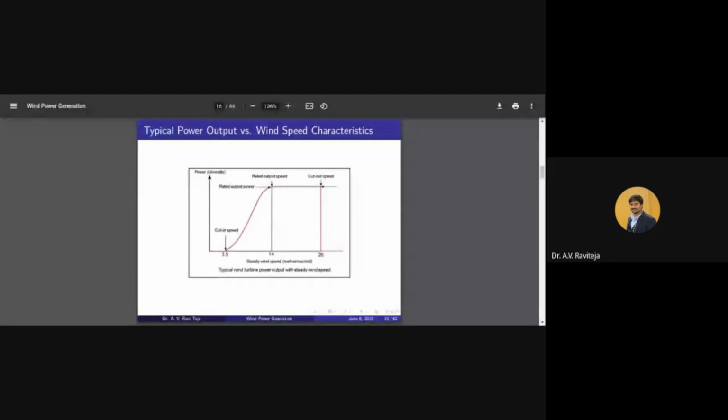We have discussed pitch angle control in the previous slides. So we'll now do opposite pitch angle control. That means we'll try to increase the drag force but keep the lift force at the rated maximum. Then onwards, I will generate only rated power. But pitch angle control is also limited. I cannot do it forever, right?